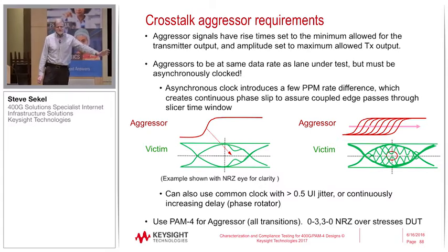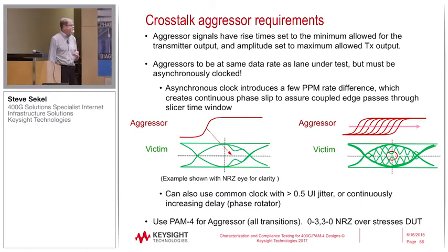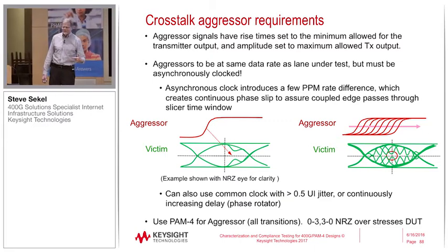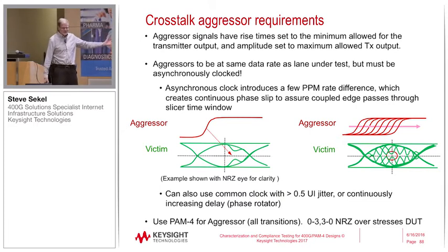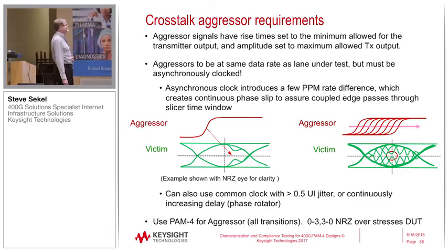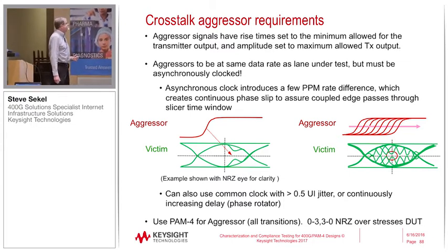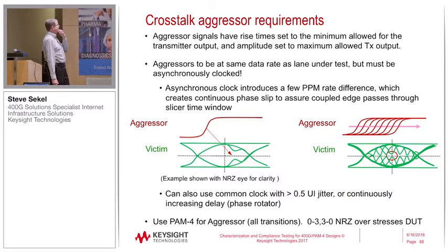And again, you need to measure that with a reference receiver that you would characterize. Those numbers for the transmitter are measured with a reference receiver. And by the way, in the current version of the OIF standards, they don't state that for the aggressor calibration. They only state it for the transmitter. And I have comments in on the drafts that are going to be reviewed next week on that very topic, because people don't catch that.